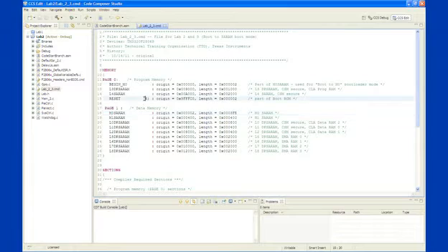You'll also notice that we are using this R qualifier here. This qualifier indicates read-only memory, and this is optional. What it does is it causes the linker to flag a warning if any uninitialized sections are linked to this type of memory. So that's a couple of interesting things between code_start_branch.asm and a linker command file.